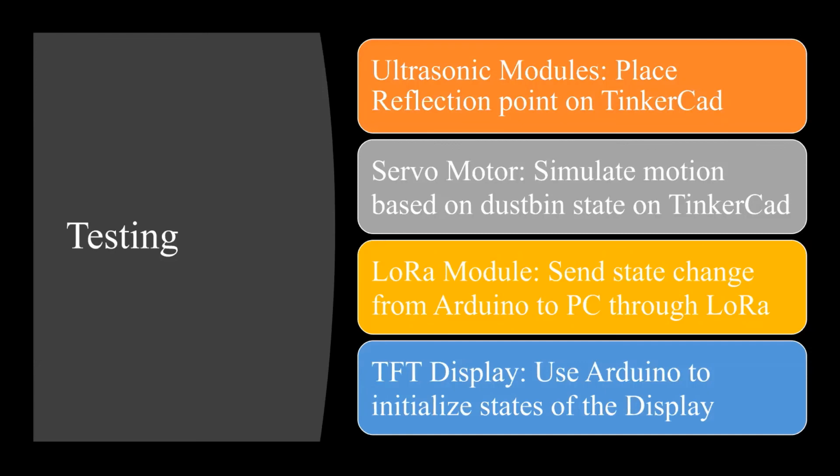To test the servo motor, we will need to simulate motion based on the state of the dustbin, whether it's to be open or to be closed. The servo motor will send pulses and will thus move. The LoRa module will also send information from the Arduino to PCs, to store the data and to store what state the dustbin is in.